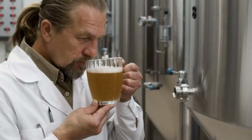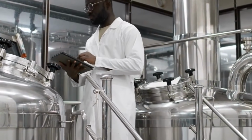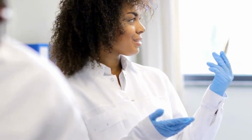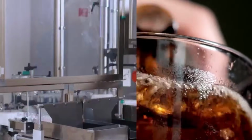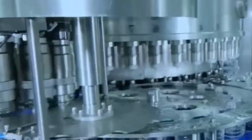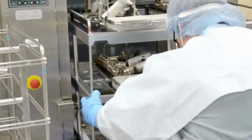The filling process begins with bottle or can preparation. Empty containers arrive via conveyor belts in nested stacks or crates. A depalletizer equipped with vacuum grippers lifts layers of containers and places them onto the in-feed conveyor. Containers proceed through a rinser unit that inverts each one and blasts filtered air or sterile water inside to dislodge debris. The containers are then uprighted and transferred to the filler carousel.